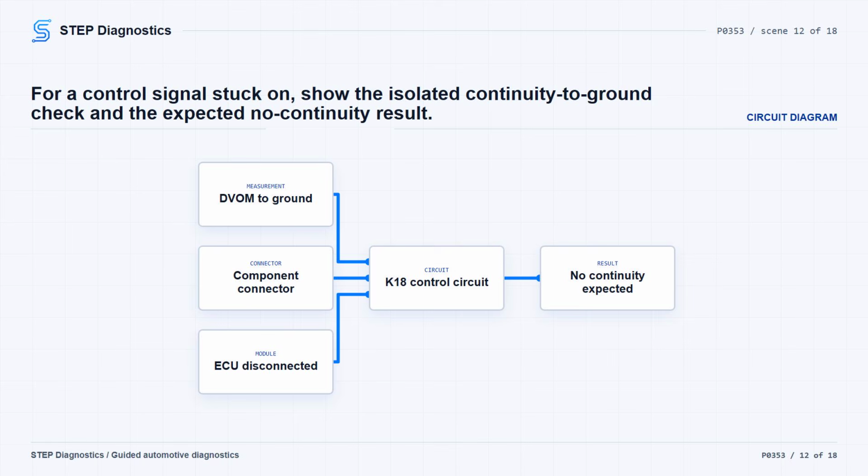If continuity is present, repair the circuit for a short to ground, using inline connectors where available to help isolate the short location. Then verify the repair and confirm the code stays gone. If there is no continuity, continue to the coil and PCM driver isolation step.